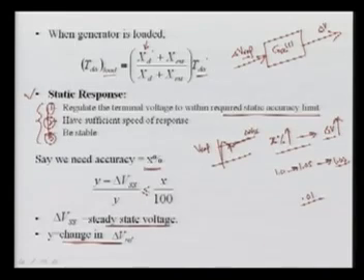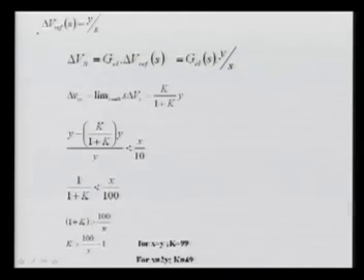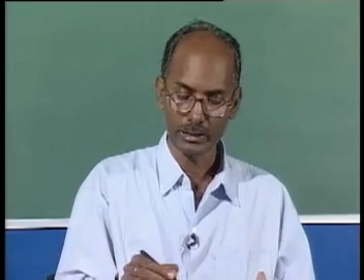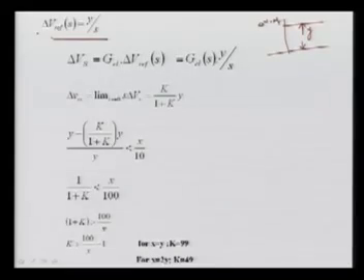Now let us see for our case, if we are changing the V reference, how the gain is related with this accuracy. To see this, let us take that there is a step change in your input. Means this reference you have changed suddenly by Y magnitude, and this is your change in Vref. Here this is your time. So if you are taking this as a unit step input, and for that the Laplace transform, we will get this change in the Vref in the S domain is equal to Y upon S.